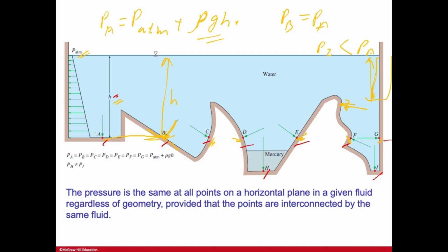If you make an imaginary liquid column, the amount of liquid column for point Z is much smaller than it is for point E or point A. You have a bigger liquid column there, so naturally the weight of that liquid is going to be larger. As a result, PZ will be less than PA.